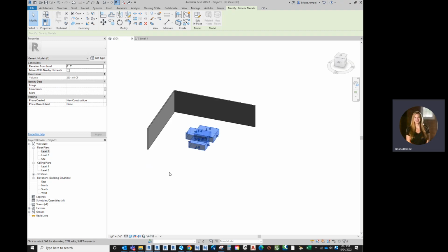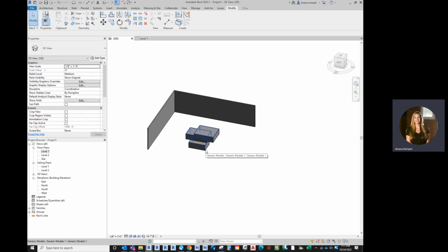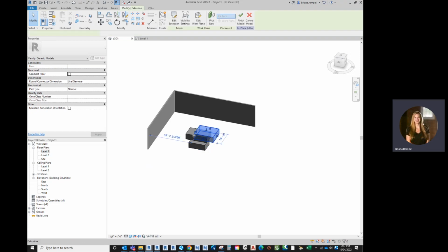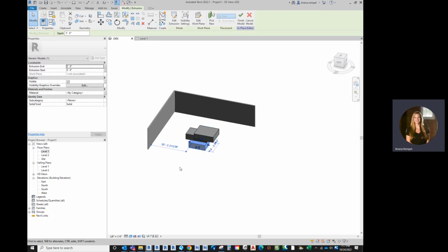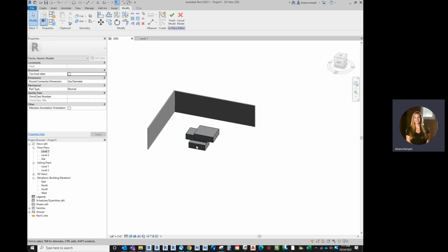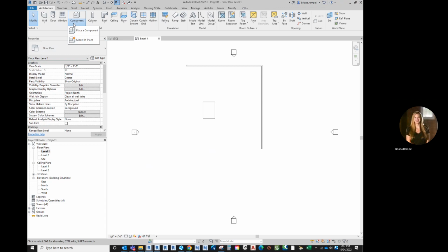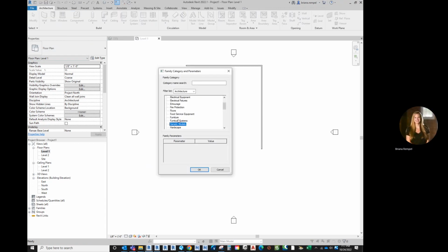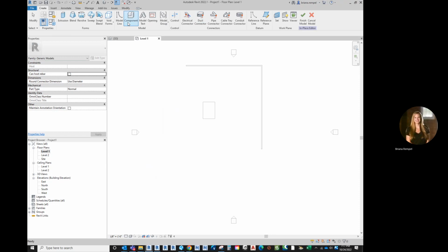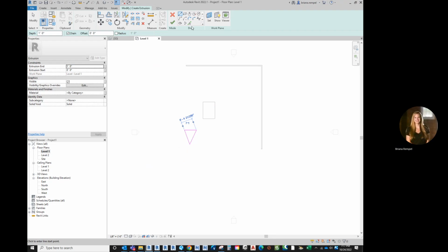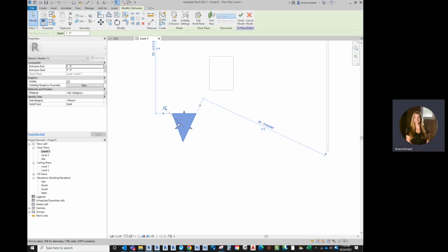You can build as many forms as you want in a model in place component. Just know that when you're in the model and building them together, they're going to be in the same model. You can always go back in and edit in place. But if I needed these 3 to be separate models, I would need to build each extrusion in its own model. What I mean by that is, if I went back to level 1, I'll create a new one here, and I'll do 1 extrusion in here. Keep in mind, it does have to be one closed path.